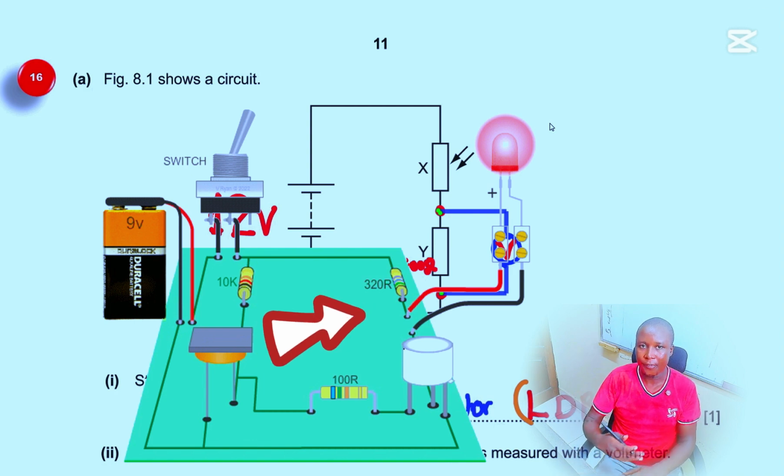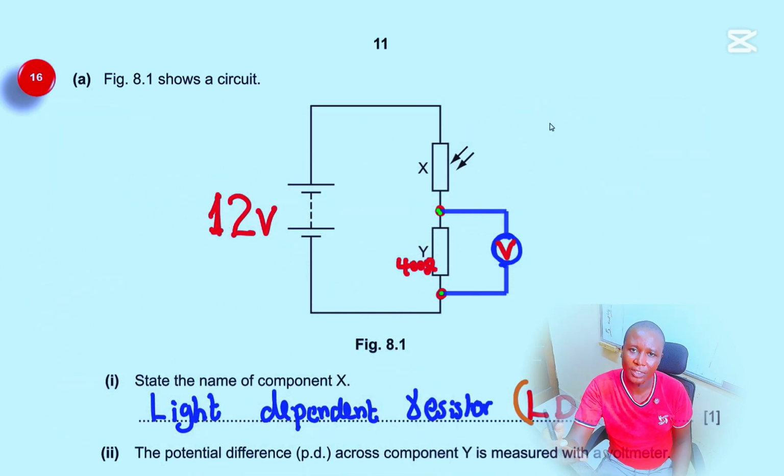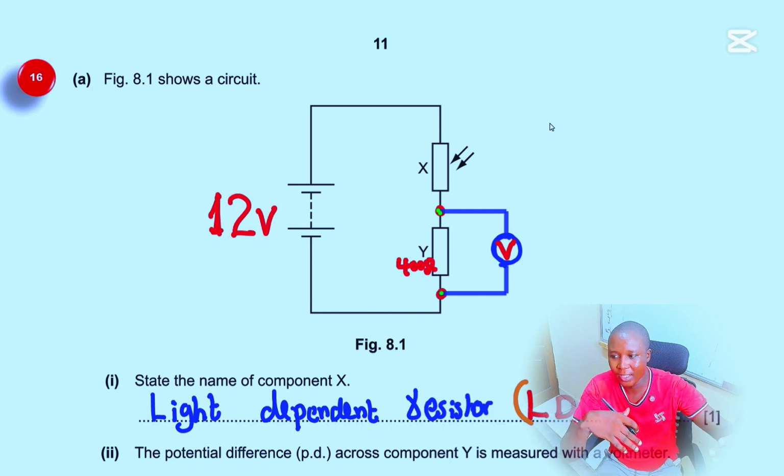Also, a thermistor is a highly temperature sensitive resistor. So if you want to apply it in a given circuit, you can put it in thermostats, whereby if the temperature goes beyond a given limit, it can switch off the current. Also, you can use it in housing for alarms.